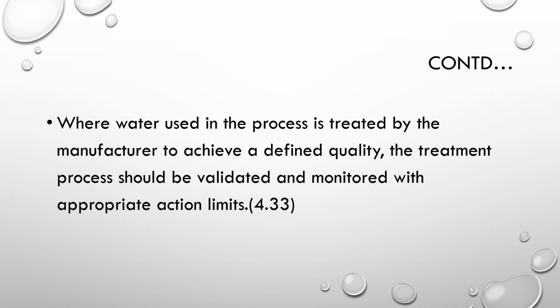If the WHO water quality is not adequate for the process, the guideline under section 4.33 prescribes that where water used in the process is treated by the manufacturer to achieve a defined quality, the treatment process should be validated and monitored with appropriate action limits. Let us understand. So if there is a requirement to purify the water by treatments like RO, demineralization, ultrafiltration, etc., it is necessary to validate and monitor the water distribution system.